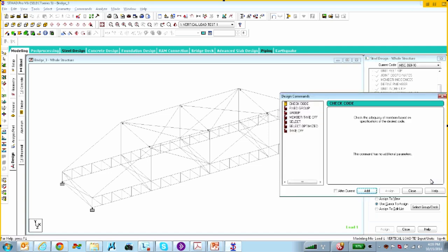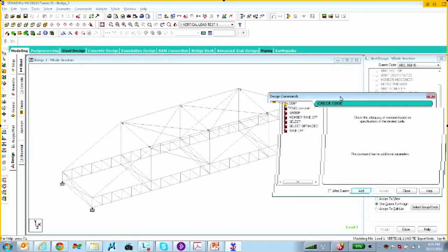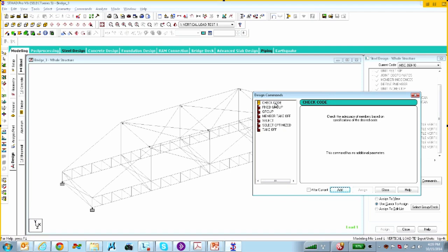So let's go over to this commands button, since you asked about optimization. And we have several different options here. Your simplest and most direct form of steel design is just to perform a simple code check, which basically means that you assign steel sections to each member. For these kinds of commands, we're going to want to use standard AISC sections. And it'll just give you an interaction ratio saying pass or fail. If, however, you want to perform an optimization, then instead of selecting code check, you can use this select command. And this is basically our way of saying perform an optimization.